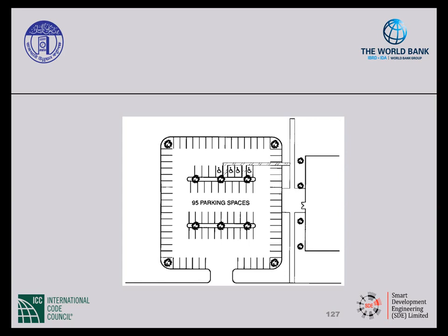Next, let's look at the access from the parking spaces to the building. As you can see, there's an access aisle that goes behind the parked cars, which could allow for a collision with a backing vehicle. And lastly, the crosswalk that goes towards the building crosses the drive aisle. So that could cause a collision with a car and someone in a wheelchair.